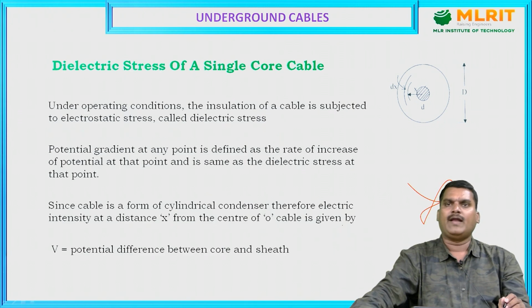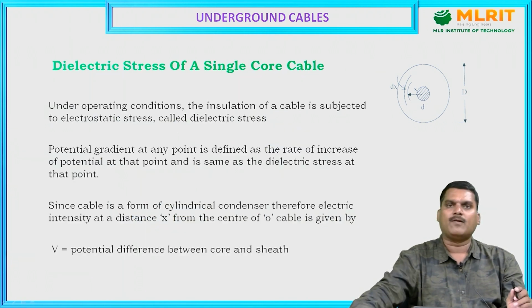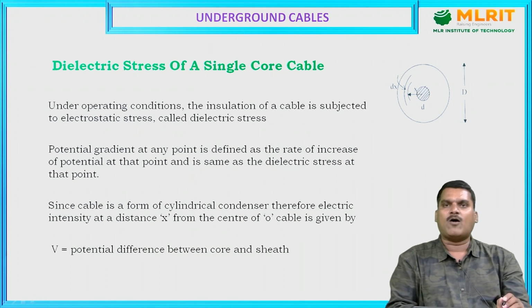Coming to the next parameter, the dielectric stress of a single core cable. This is one more parameter we need in the case of underground cable. Under operating conditions, the insulation of the cable is subjected to electrostatic stresses. If you keep operating the underground cable for power carrying purposes, the cable undergoes electrostatic stresses. That electrostatic stress is called dielectric stress.